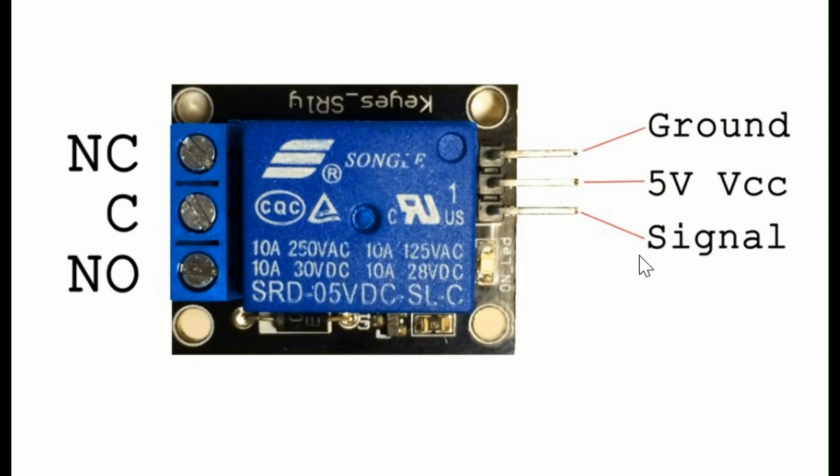So when it receives a positive signal, which is 5 volts, if initially the connection was normally closed, it will turn to normally open. If it receives a signal which is 0 volts, if the connection was initially normally closed, it will remain normally closed. So that's the way. If the signal is positive, it switches from normally closed to normally open, or normally open to normally closed. But if the signal is 0, nothing is done. The status remains unchanged.